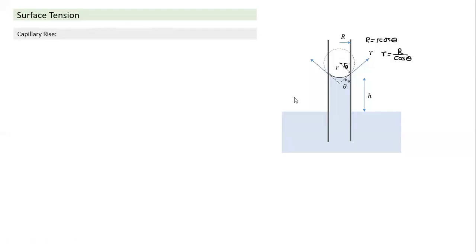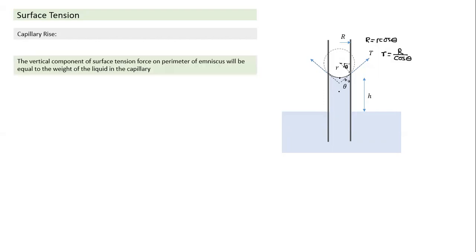So this is a capillary rise. There we can understand in two different ways. H is the height of the capillary, and when we take H height, we take it at the bottommost point here. That's H we take here. So there are two ways to calculate capillary rise. One way to understand is to take this particular liquid which is in the capillary. What is the liquid which is part of the capillary? If we draw a horizontal surface at the same level as the surrounding liquid, this whole thing is the capillary rise here.